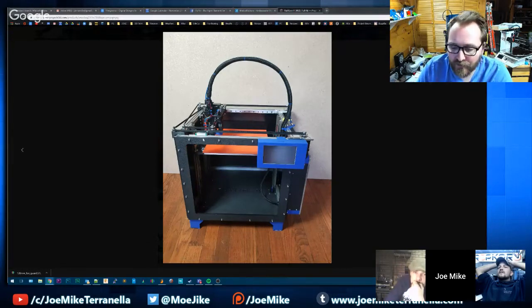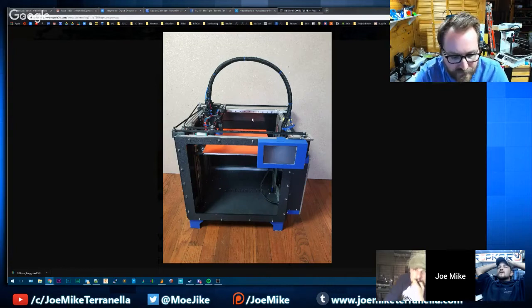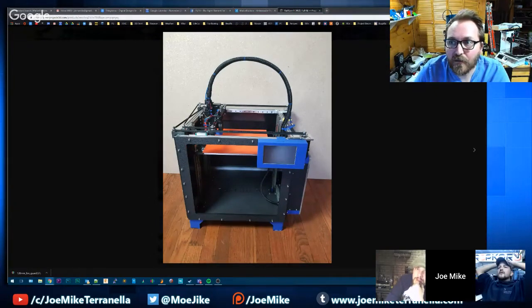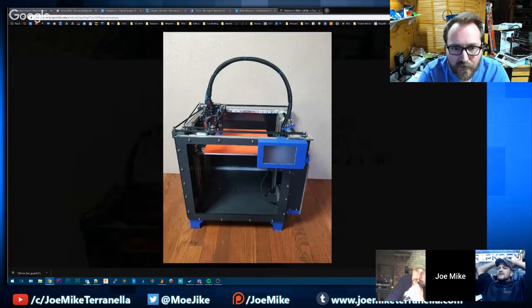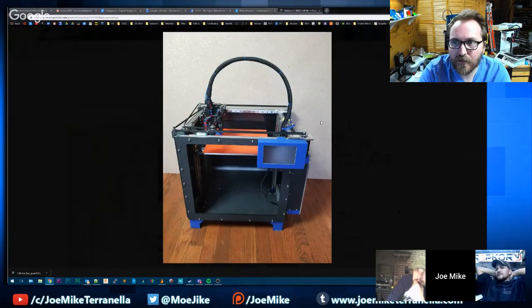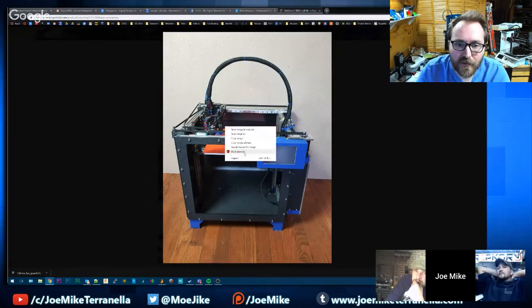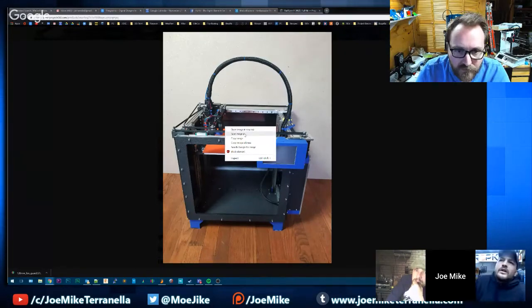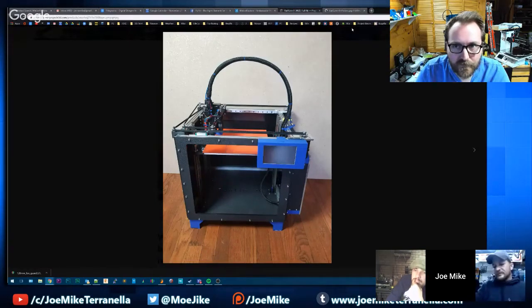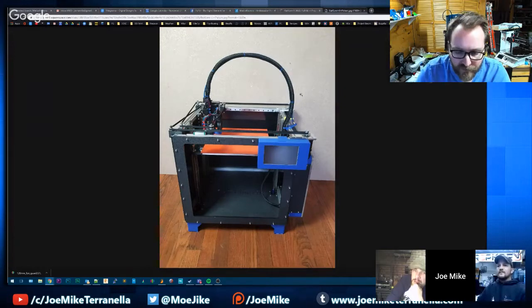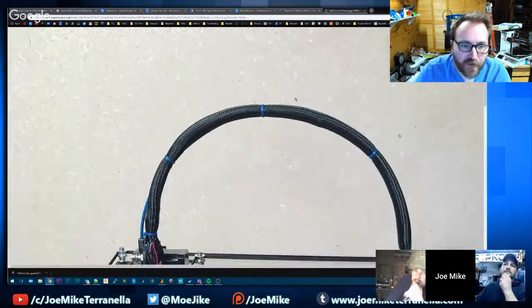Here's the funny part about this. And that's using GT2 belts? I believe so, yes. So they're probably not steel reinforced belts or anything. Can I not zoom? Come on. Can you get GT2 with steel cabling in them? You can get, yeah. Can you? Okay, I've seen that if they have steel cabling, you wouldn't have as much backlash then. Yeah, you can get them with Kevlar in it. Kevlar is pretty sweet. There we go. Okay.